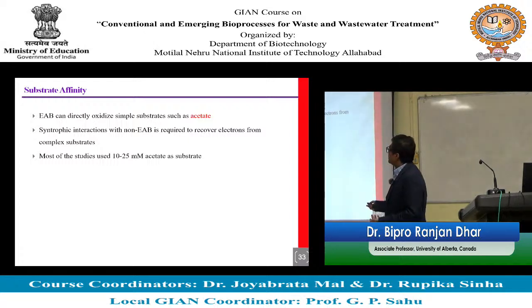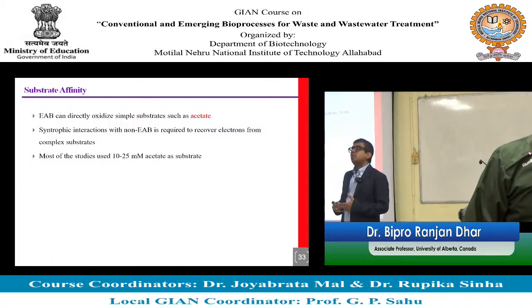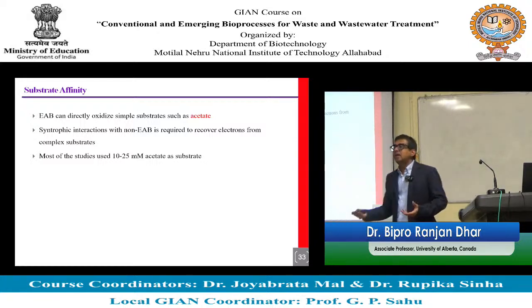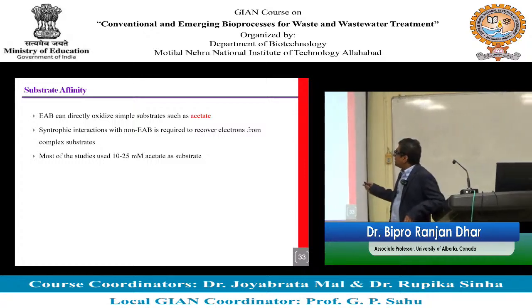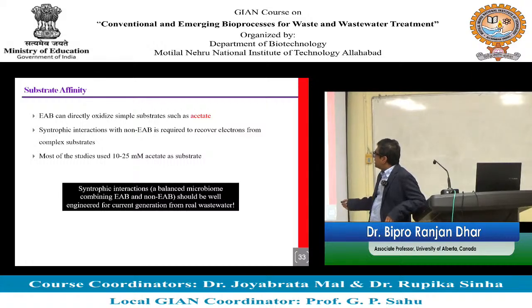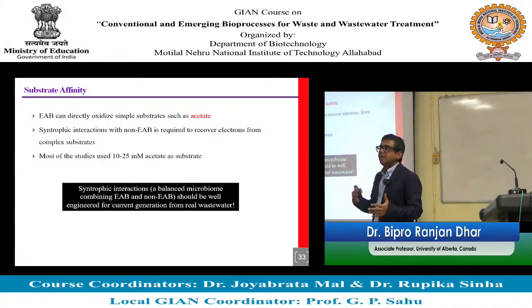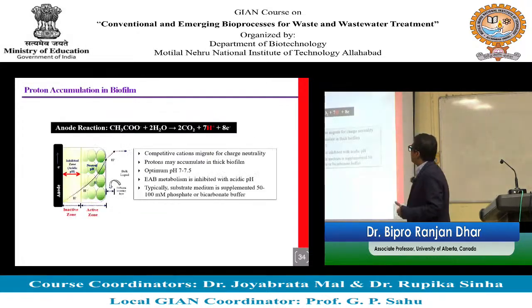But most of the studies in this area, okay, have been done with acetate as a substrate. And why is that? Because we know that acetate can be directly utilized by microbes. So for some fundamental studies, acetate has been widely used as a model compound. But for real life, you have to make sure that you have a balanced microbiome in your biofilm. You have both non-EAB like fermentative bacteria and electroactive bacteria, especially when you want to design something for real wastewater or complex wastewater.